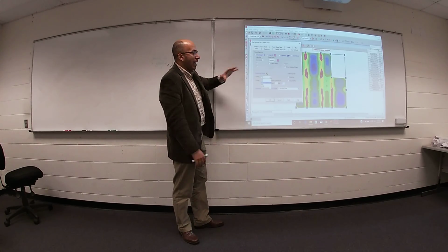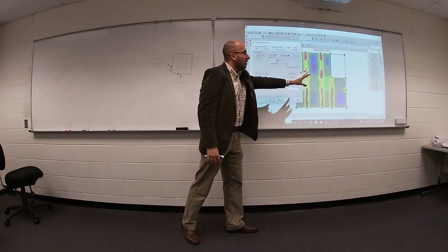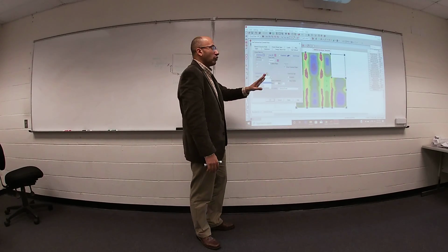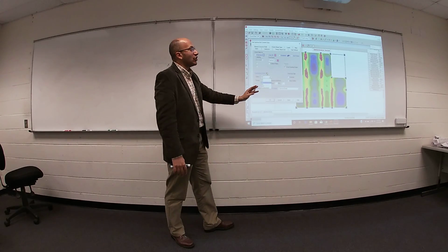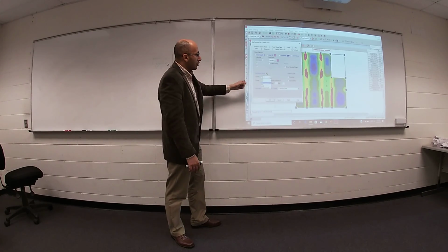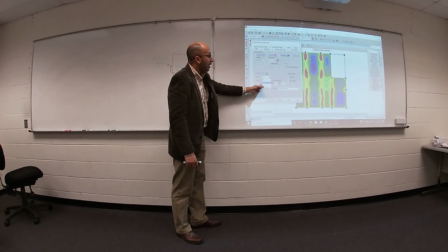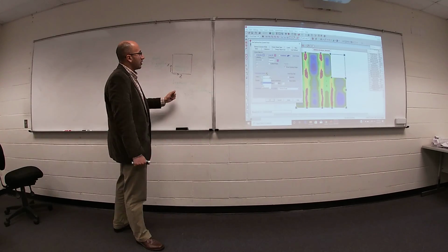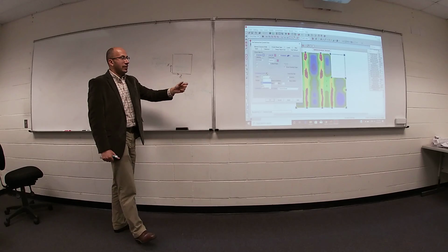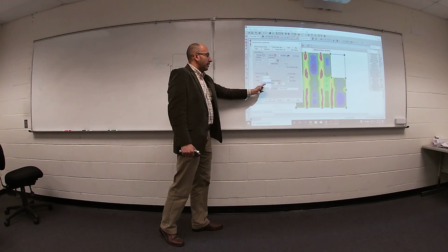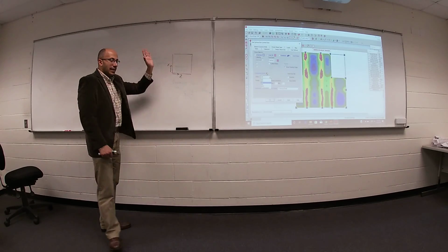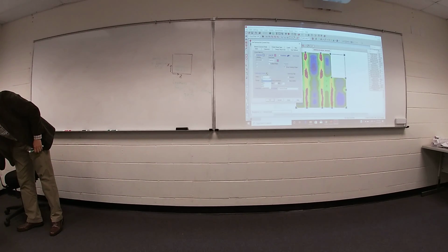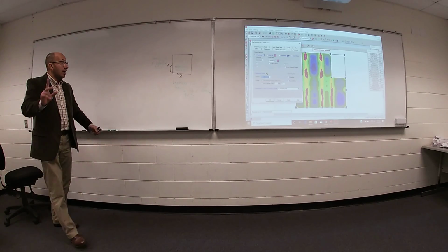But we have no problem with shear in slab. Our concern in slab is only for moment. We don't care about torsion, we don't care about any shear, nothing. So the only two options I will use: MZ to get my reinforcement in Z direction, MX to get my reinforcement in X direction. Any questions so far?